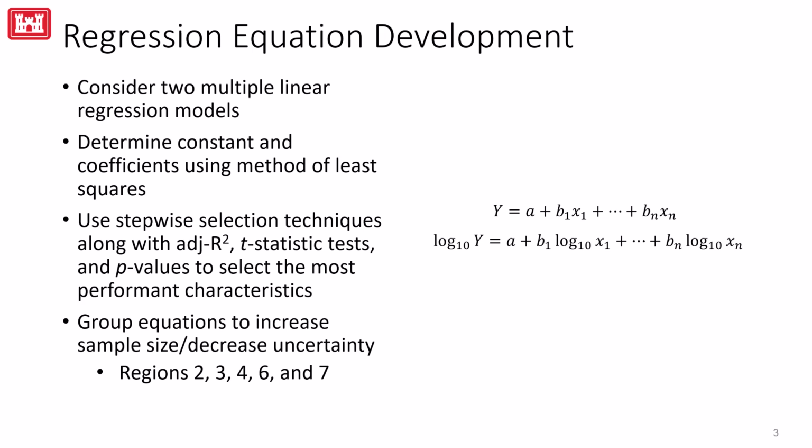When using multiple linear regression with several watershed characteristics, some of the proposed characteristics may have little to no effect on the dependent variable of interest. When this occurs, these characteristics were removed from consideration. In order to simultaneously evaluate the effectiveness of the regression models and avoid overfitting, an adjusted coefficient of determination, called adjusted R-squared, was used. The nice thing about this metric is that its value increases when a new term improves the regression model more than would be expected by chance.